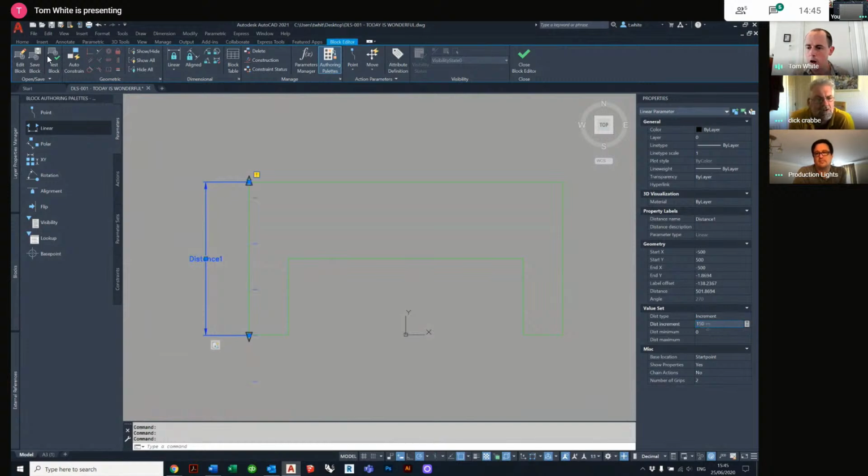Yeah. So this screen with the grey background, it's called a what? Because that's the bit that I have no access to in my cheap program. It's called a block editor. Block editor. Thank you. Yeah. And there are 2 ways of editing a block. There's edit block in place, or there's a block editor. I believe the edit block in place is useful for so many tools, but it's not useful for the parameters with the annotation or attributes we're talking about at this stage.